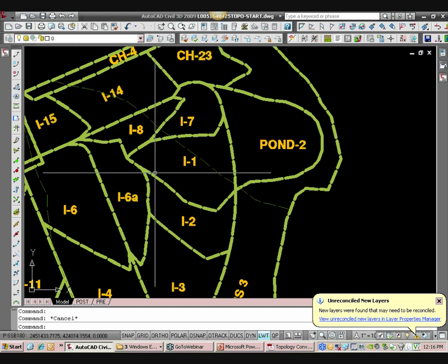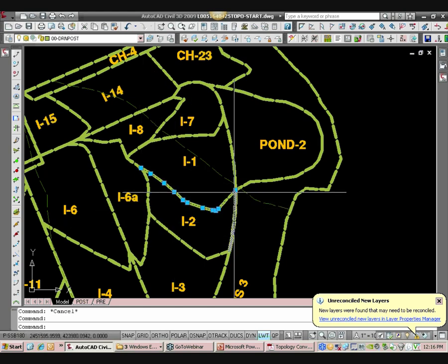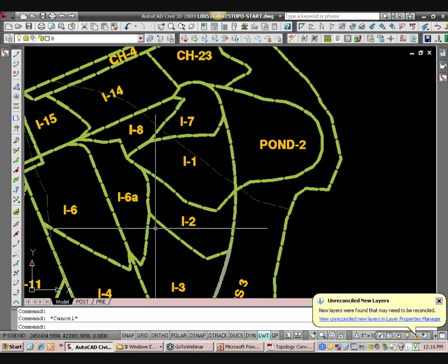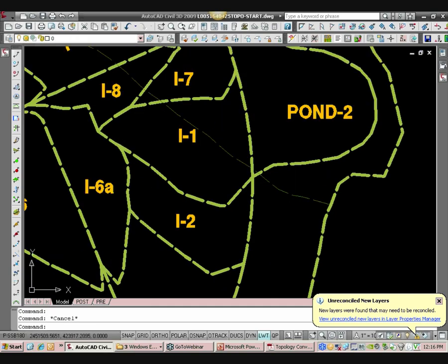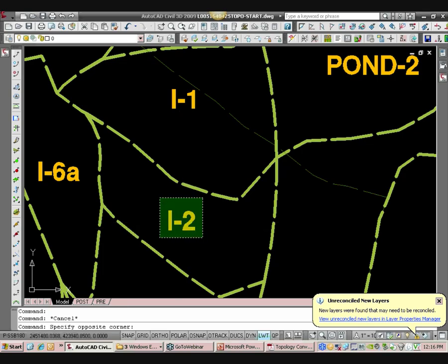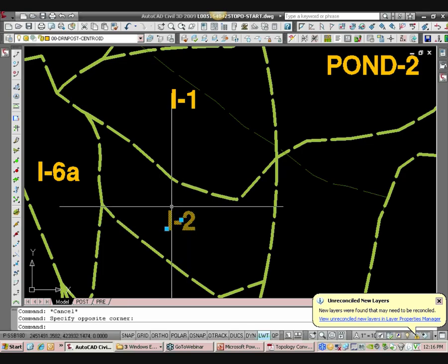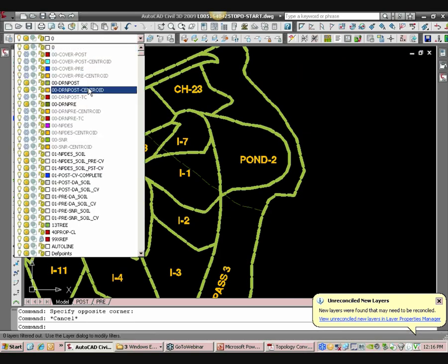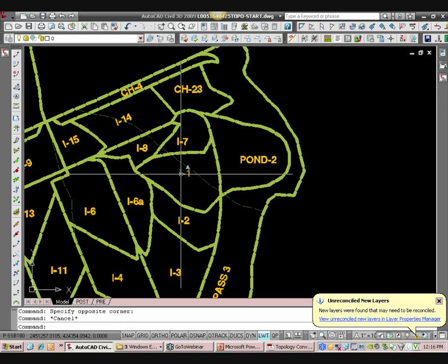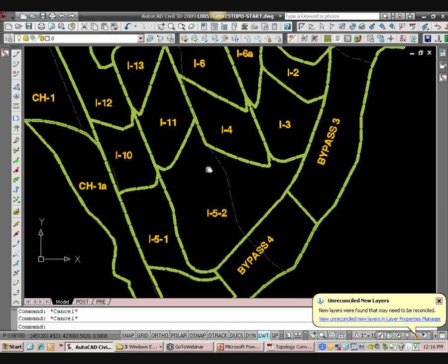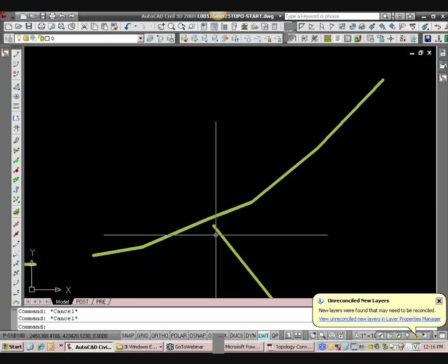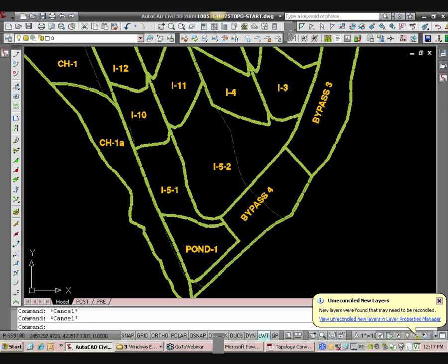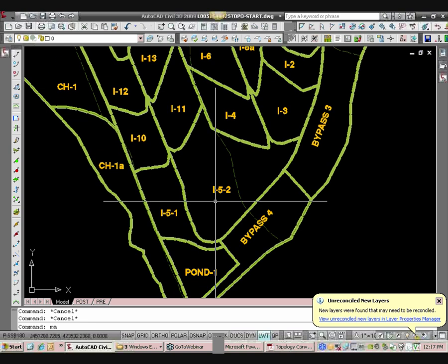These line segments that are linked together here are called links. When links encapsulate a piece of text that has object data, that's called a centroid. So this is now our centroid, okay? That's where you see some of these terminologies up here. So these are just terminologies to keep in the back of your head. So to clean this stuff up, this one needs to be extended to touch in here, and so on and so forth. We can use a command called map clean, okay?